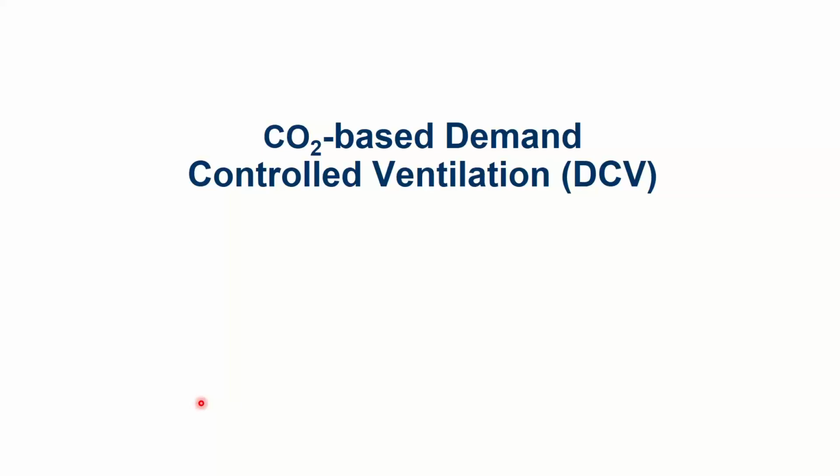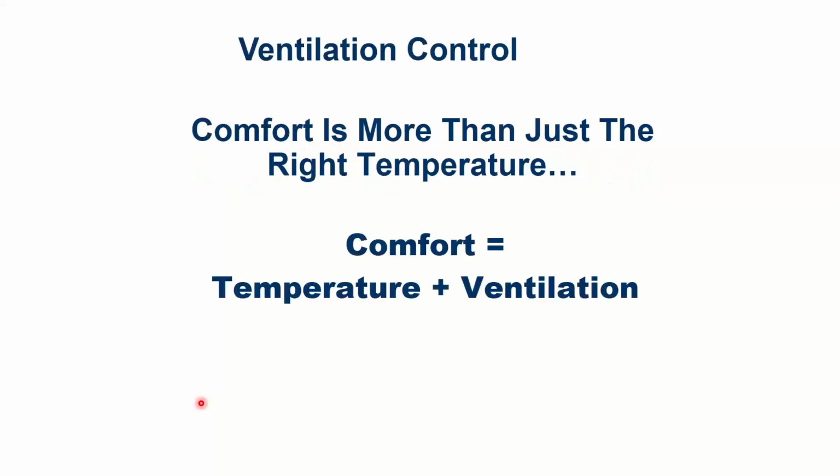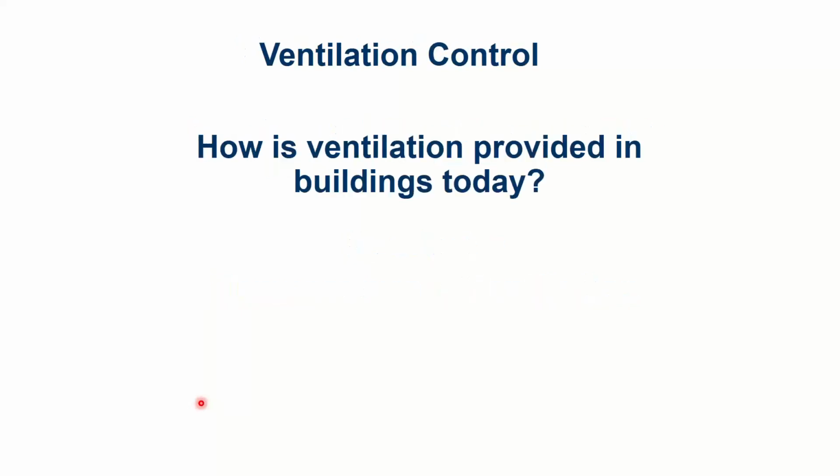Got all these standards that want you to have fresh air. Got these other standards that want you to save energy, and they're crisscrossing. Where's that middle point that I can do both of those things? This kind of helps me do that. So we're going to make sure that we're looking at temperature. Ideally, I should add humidity to this. Temperature, humidity, and ventilation. If I get those three right, that's like the trio of magic that can happen.